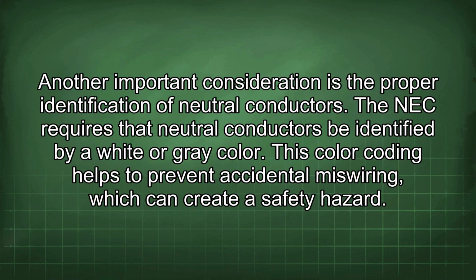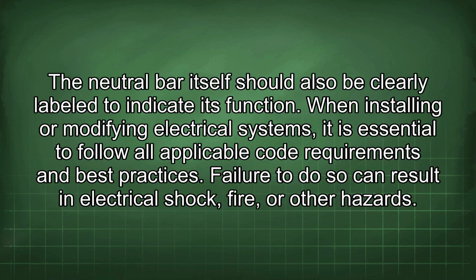Another important consideration is the proper identification of neutral conductors. The NEC requires that neutral conductors be identified by a white or gray color. This color coding helps to prevent accidental miswiring, which can create a safety hazard. The neutral bar itself should also be clearly labeled to indicate its function.